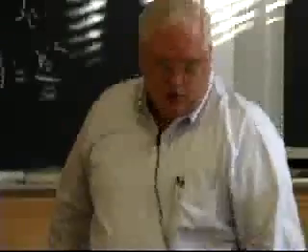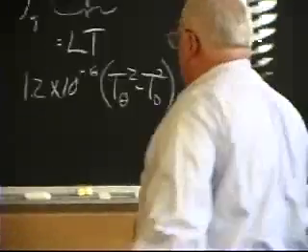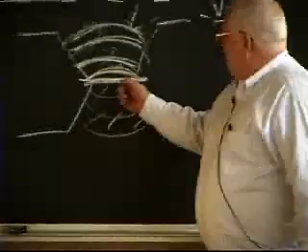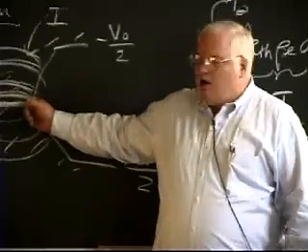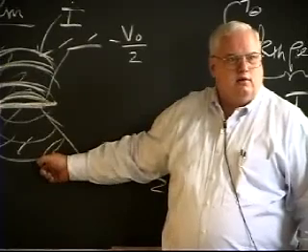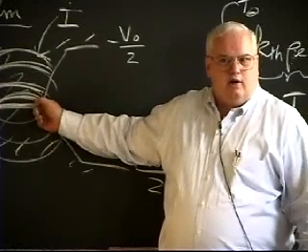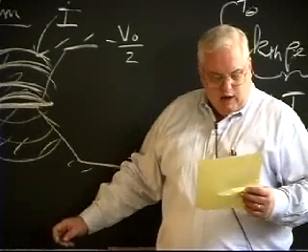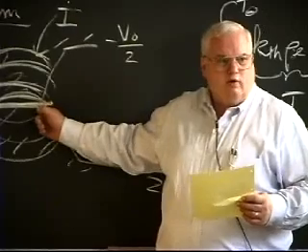It turns out the melting voltage for aluminum, which melts at 660 C: to get to 660 C right here, you need 3/10 of a volt applied across here to melt that asperity. For copper, you need 0.43 volts.